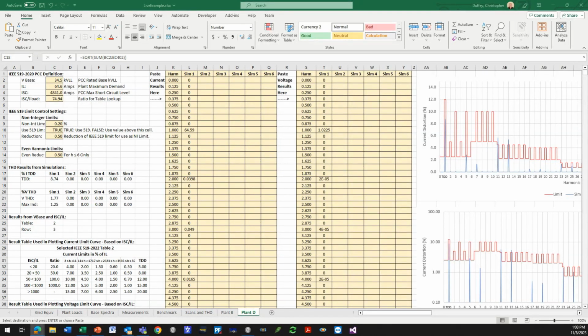some manufacturers will include the current injection and that filter and their smoothing reactor from their inverter bus to the AC bus. They'll include all of that in the Norton equivalent. So I would suggest that method first. Ask for the complete Norton equivalent looking from the very exterior with all the internal, whatever they have inside. Get that Norton model at that connection point, the point of connection. And that should be a complete representation of everything behind it.